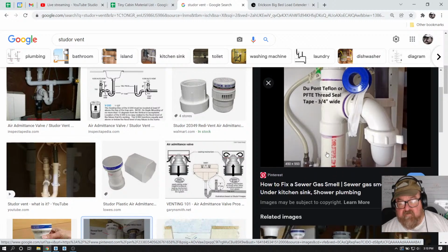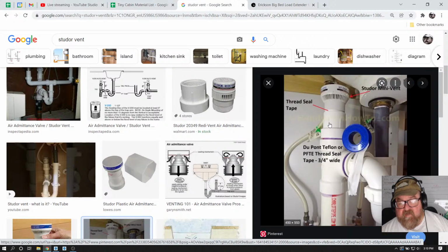And of course, if you have a volume of water that fills up the entire pipe, that's the case. If you just have water going down the pipe, that's not the case. But in most cases, you would have a lot of water going down the pipe, and it would need a vent. A lot of people think the vent is for the air to go out, but it's mainly so the air can be sucked in, because your water is draining down and pulling air in. In this case, it won't allow the sewer gas to come out because it's got that little rubbery diaphragm up there.